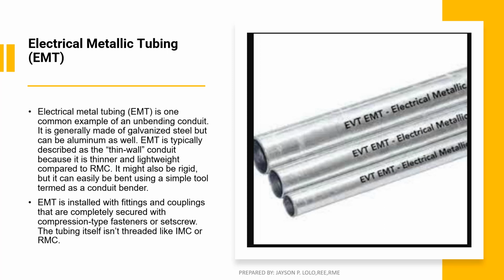In the industry, EMT is used for auxiliary wiring, for electronics wiring, such as for telecommunications, for telephones, and for smoke detector wiring. Furthermore, the standard sizes available for EMT include 1 inch to 1.5 inch only. Take note of that. It can be used in exposed indoor wiring, where EMT is generally used because it often runs in light commercial or residential construction.